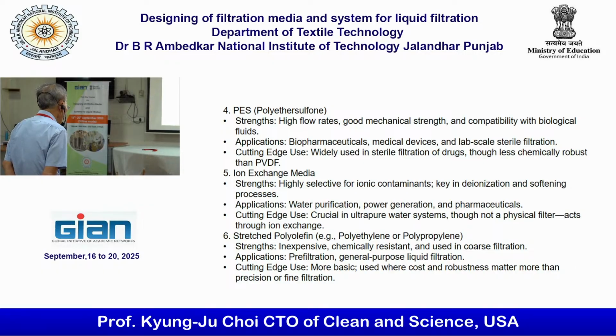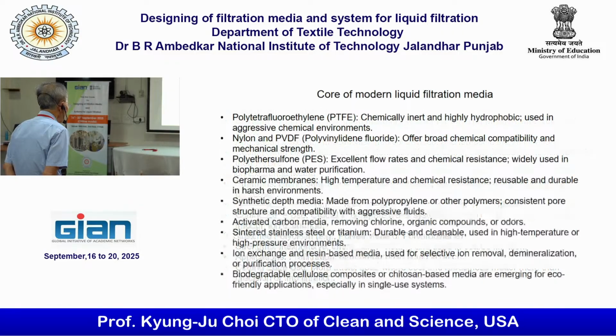What about the stretch polyolefin? So it's inexpensive, chemical resistant, but application is pre-filtration because the efficiency is not as good as the EPTFE. Use where cost and reversibility matter more than precision or fine filtration. So the core of modern liquid filtration media, polytetrafluoroethylene. This is a bit different one. It's not EPTFE. Even though PTFE itself, you can make by solution casting or different processes, it's nothing to do with the EPTFE.